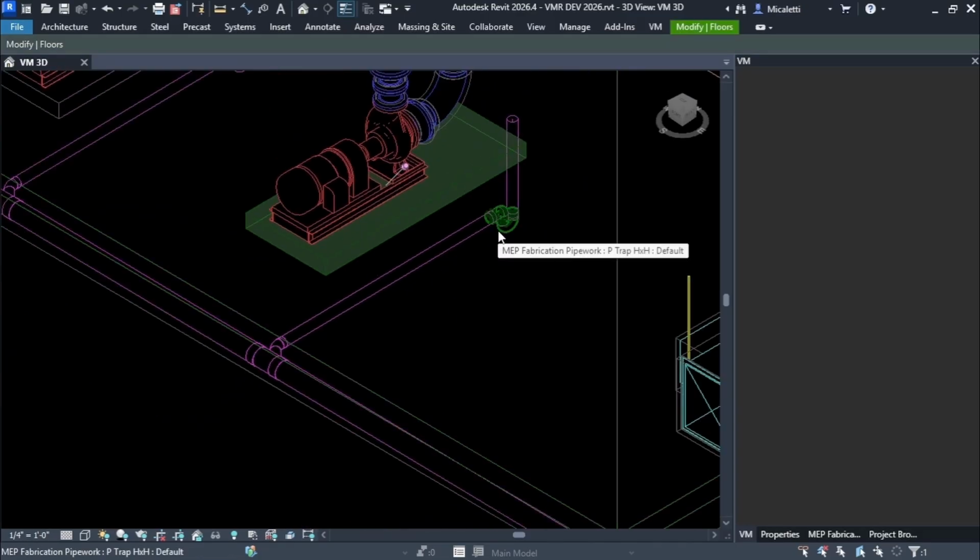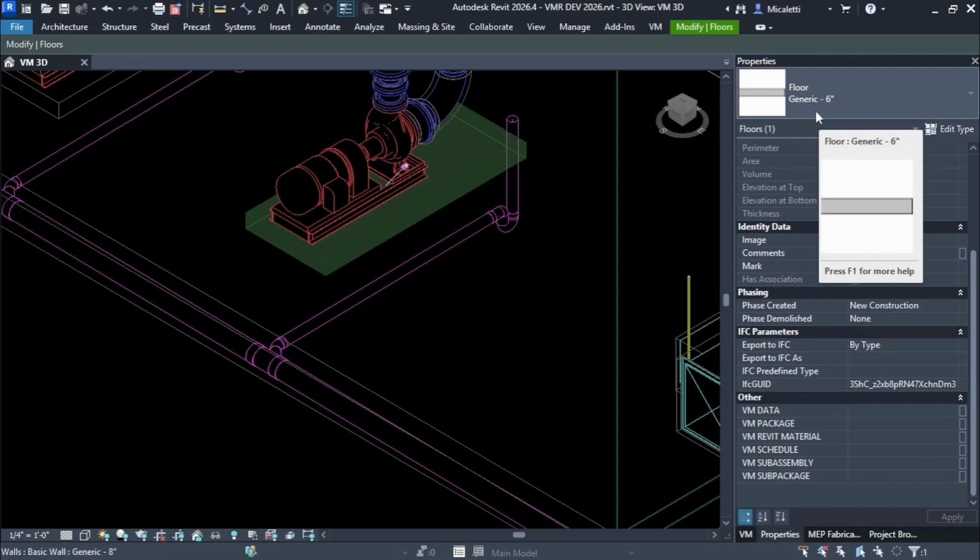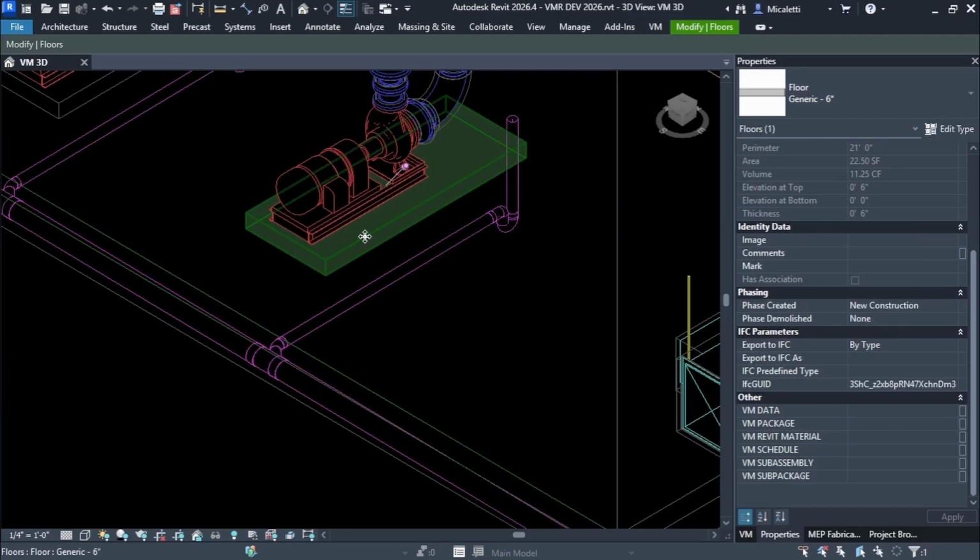Now here's the thing. This is a Revit floor. So it's a built-in family. You could make a family for housekeeping pads, and you could put a connector on it, right? Just a dummy connector, and then you get points for free. And then you'd be scheduling the housekeeping pad, which means you have the size along with the points. It's not just this separate family.